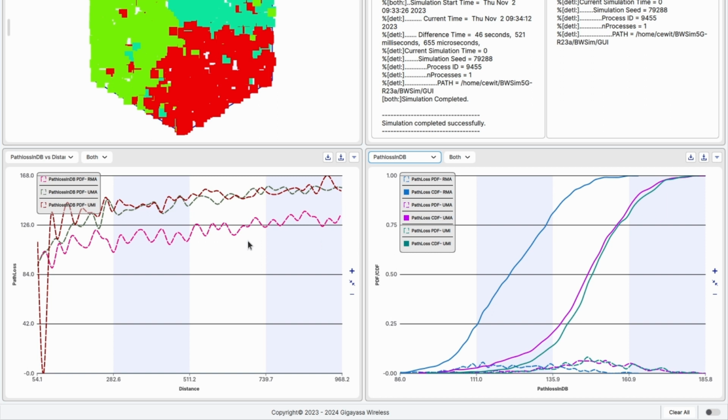One thing that can be noted here is the sharper increase in path loss. It can be noted that with increase in distance, the increase of path loss is much sharper in the urban scenarios than in the rural scenario. This can be attributed to the fact that as the distance increases, the different structures that contribute significantly to the path loss also increase, leading to this sharp increase, or to put it in other terms, the rate of change of path loss is higher in the urban scenarios.